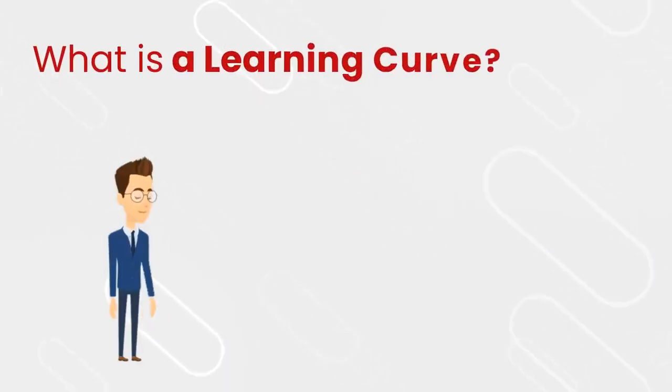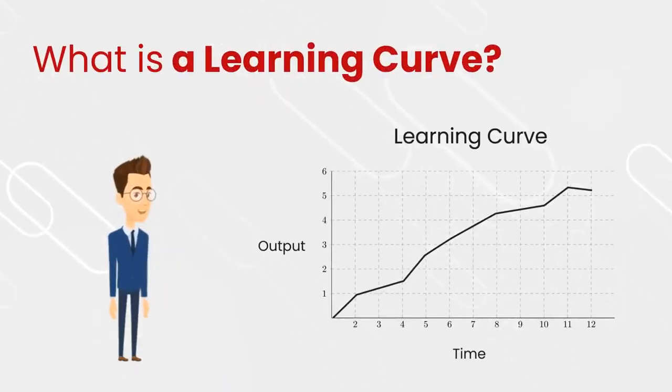In the apparel manufacturing industry, a learning curve is generated for sewing operators' growth in performance. When a new style is loaded to a line, the sewing operator takes time to reach her normal speed of stitching. A learning curve is a graphical representation that shows the relationship between output of a product and time. The target of a learning curve is to find out how the performance of the workers is improving over time.